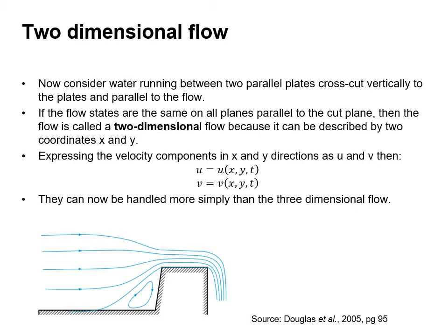In two-dimensional flow, it is assumed that the flow parameters may vary in the direction of flow and in one direction at right angles, so that the streamlines are curves lying in a plane and are identical in all planes parallel to this plane. Thus, the flow over a weir of constant cross-section is shown below, and infinite width perpendicular to the plane of the diagram can be treated as two-dimensional.